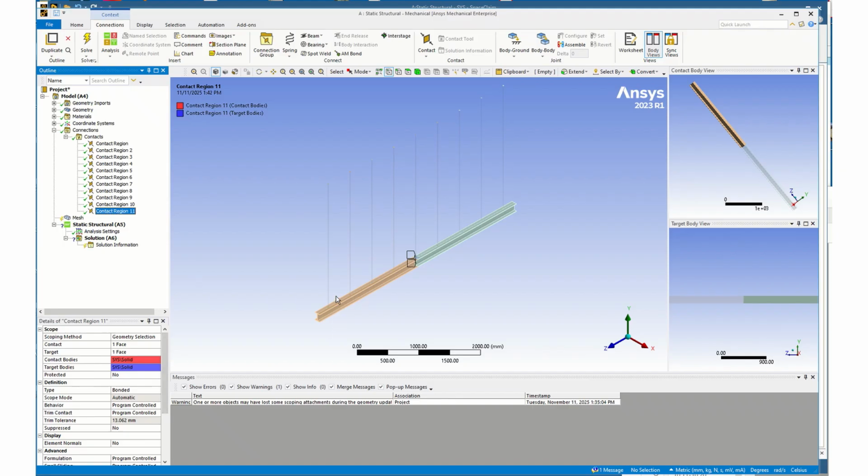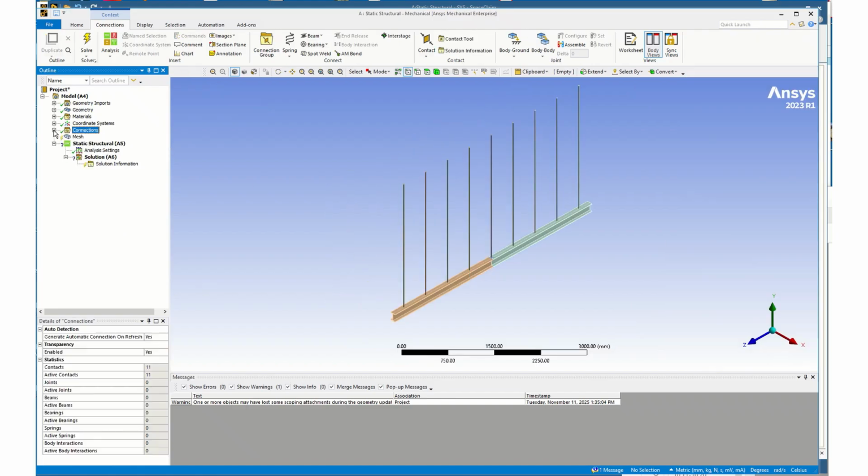If you knew more specifics about how these rods were connected to the beam, you could model that, because right now there is going to be a bending moment allowed here in this rod, and that may or may not be actually what you have in your scenario. So I'm going to go ahead and close the connections, let them be what they are.